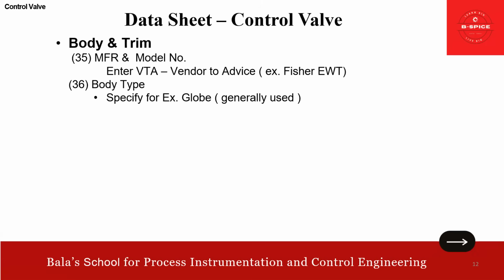For example, the fluid properties, pressure drop across the valve, shutoff pressure required, the stroke speed, application service, sound level of the valve, the seat tightness, and of course economical advantage. In that sense, rotary valves, meaning eccentric plug or segmented valve, may substitute globe valve and be used for slurry service.